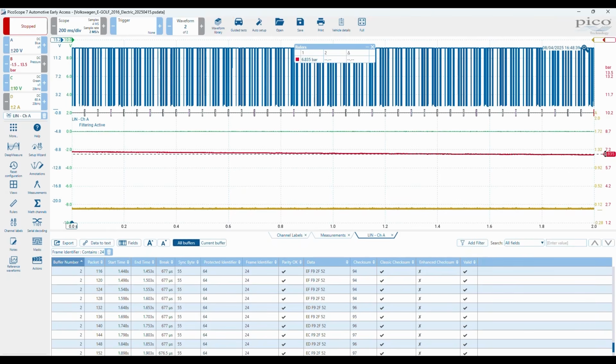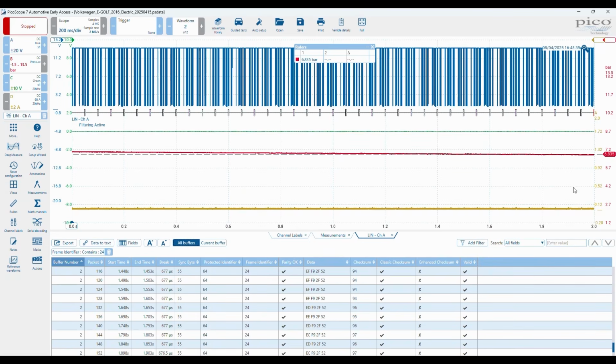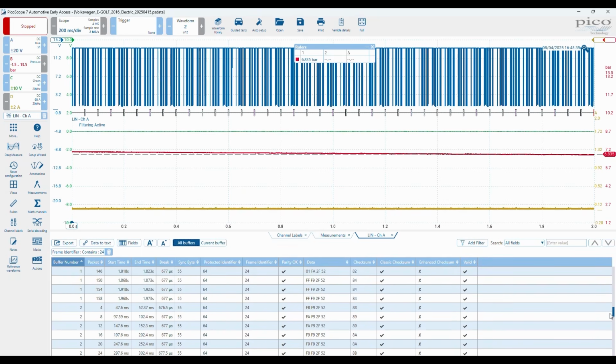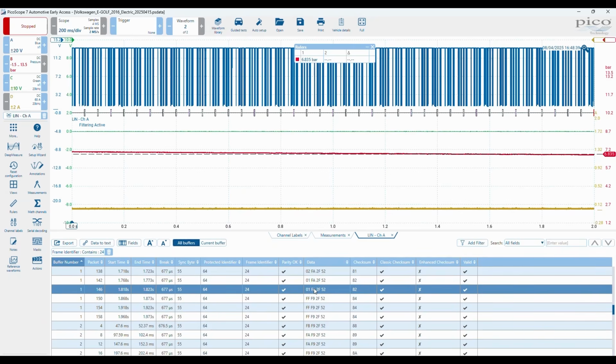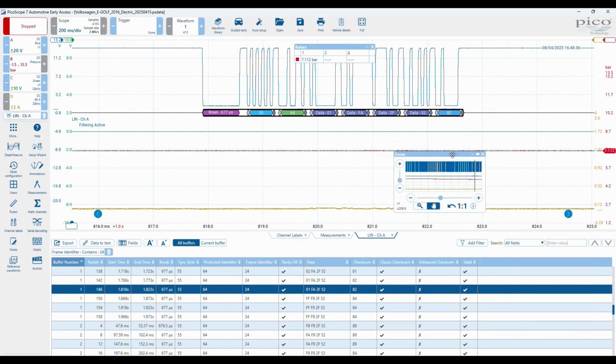So as it would seem, certainly pressures round about 6 bar or heading towards 6 bar utilize the first byte, but when you get above that, let's see if we can work out where we get the change. So where does F9 become FA? There it is. If we double click and then move the ruler, it would appear we move over at 7.112 bar.